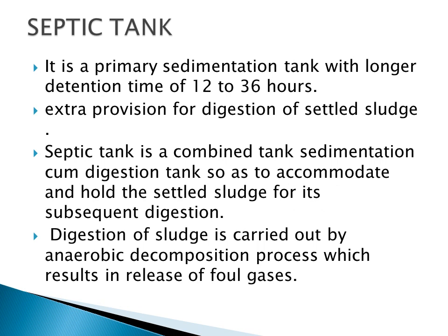So coming to the septic tank, it is nothing but a primary sedimentation tank, and here we are providing a longer detention period of 12 to 36 hours, that is 1 day to 3 days. This detention time we are providing. And here an extra provision is given for digestion of the settled sludge. The sludge will be settled at the bottom of the tank. So that extra provision for the sludge deposition we have to provide when we design the septic tank.